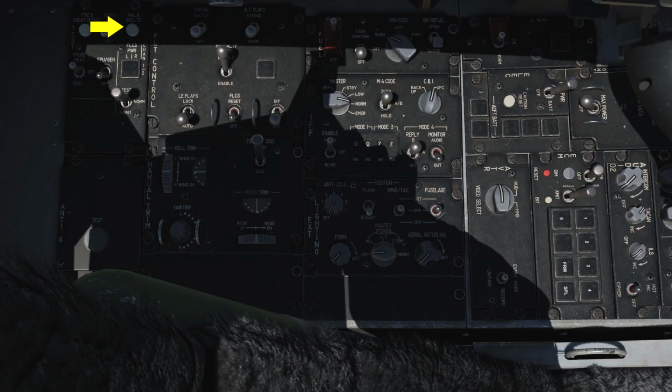An indicator light test button that tests the warning and caution lights, as well as the audio voice messages. The flight control system, pronounced FLICUS, a power test switch for the left and right A, B, C, and D light indicators for the 4 redundant flight control channels. Below it is the FLICUS test power switch that, when held to test, tests power output to the FLICUS when electrical power is first set to battery. Now, prior to an engine start, you would test the FLICUS first.